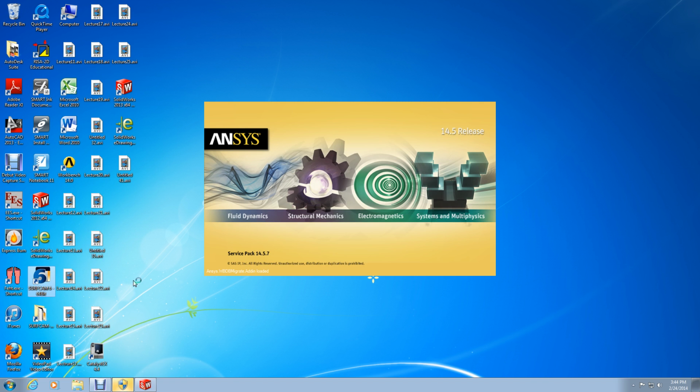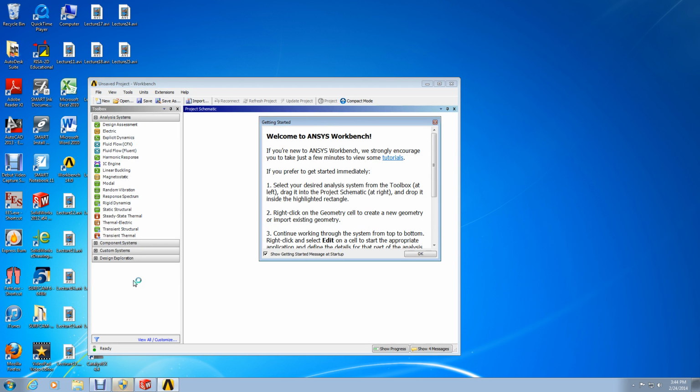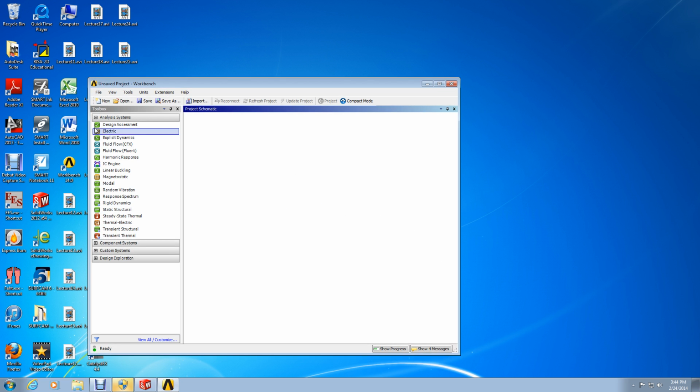Now in ANSYS there is a simply supported option, as you can see. But in order to use it, it has to be a two-dimensional problem for ANSYS to recognize it. So what we're going to do is form a surface in SolidWorks instead of a 3D body. We can actually do it two ways.